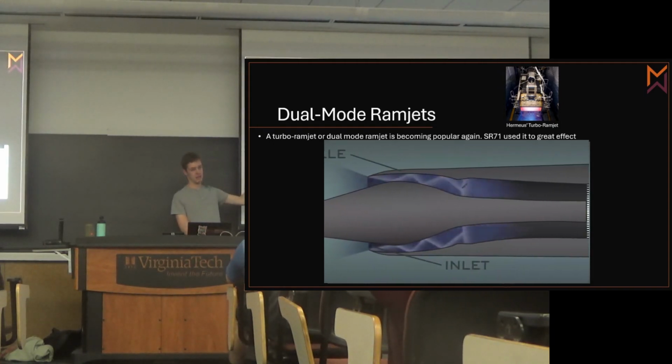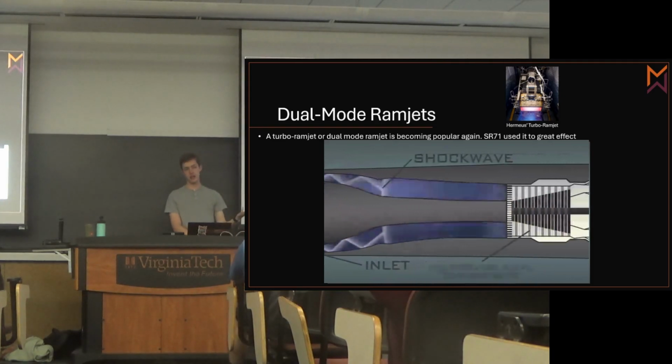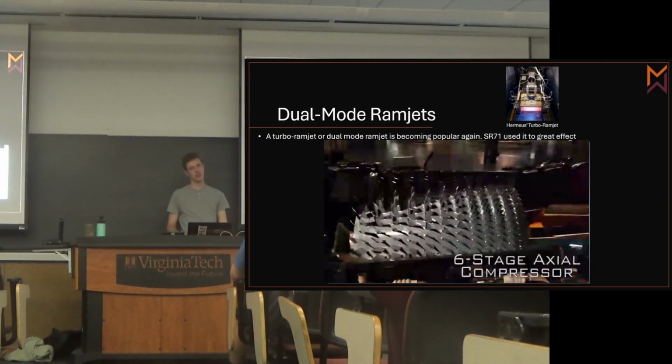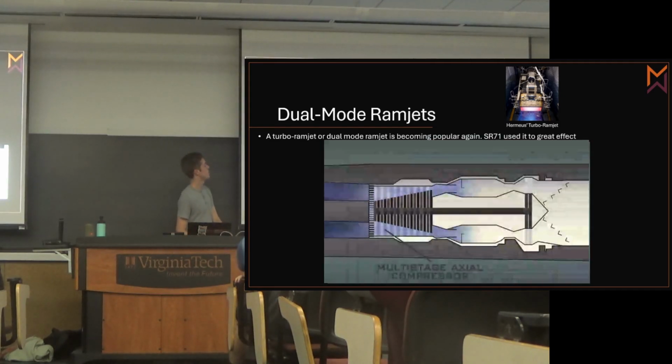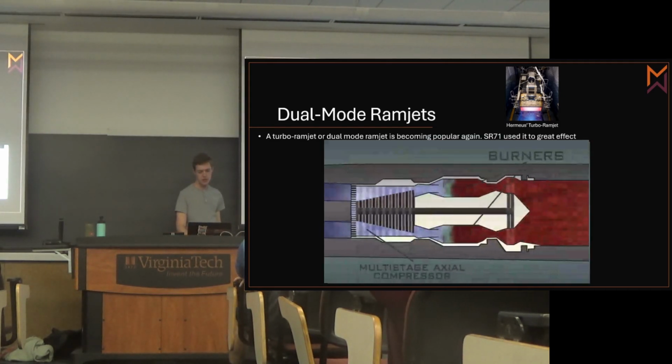So with that principle, I can make a ramjet instead. No blades, I can go faster. Nothing to burn up except the skin of the aircraft, which will be the next problem. But that lets us go a little bit faster.